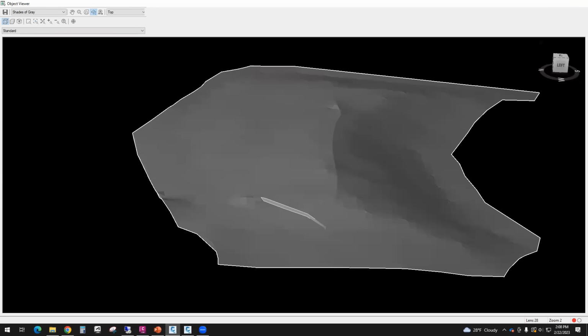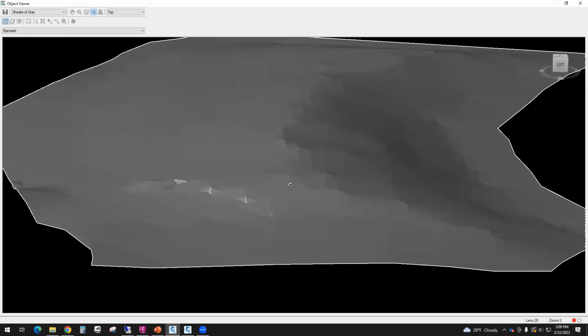Okay, so specifically when you use smooth surface, you want to make sure you have break lines at those important locations. And we still have top and toe, but it doesn't know to hold the line all the way across the top and hold the line all the way across the bottom. So it just smooths across this way.